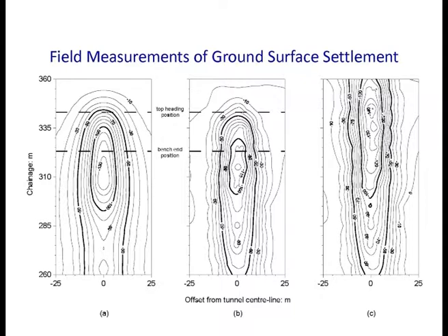So the important thing it tells us is actually your 1-2 meter is not going to affect the whole thing. The most important thing is how fast your shotcrete is hardening, because it affects the next 20 days and therefore the next 20 meters. So basically what it tells you is this. In fact, if I'm digging the heading here, the maximum settlement is 20 meters behind me. It's 20, not 2 meters behind me. You know, and that is the thing.